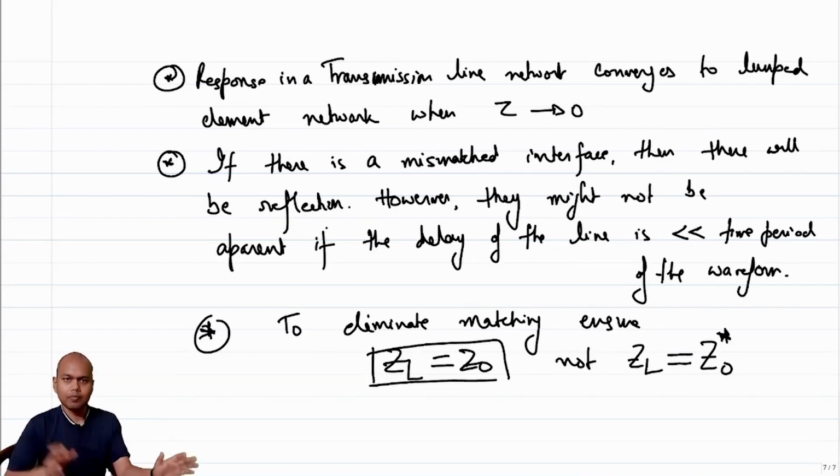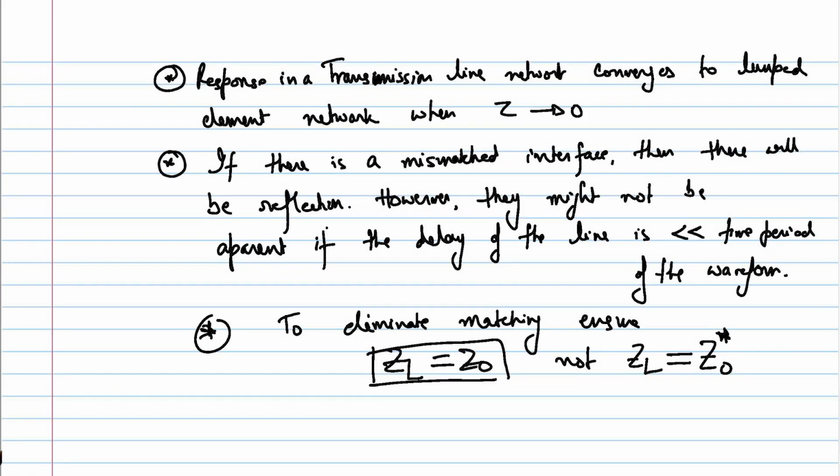We know that for a given source impedance, the load impedance should be complex conjugately matched. That ensures maximum power transfer, but that does not ensure no reflection. So that's why this is called a reflection match, and that is called a power match, right? Whatever we have been talking about till now is essentially reflection match. Strictly speaking, this is not a power match. Okay.